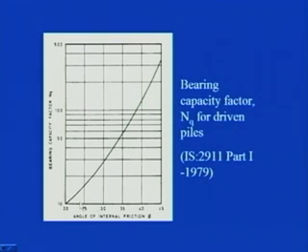So, you go to x axis, pick a value equal to 30 degree, then you move along this vertical line wherever it cuts this particular curve. You see this is the curve, you move along this 30 line, wherever it cuts here you read the corresponding value of NQ, and that value you can use safely for all the computation process. Let us say there is some value between 30 to 35, that is let us say 32. So, you approximately read where this 32 will lie on this particular axis, go here, read the corresponding NQ value.